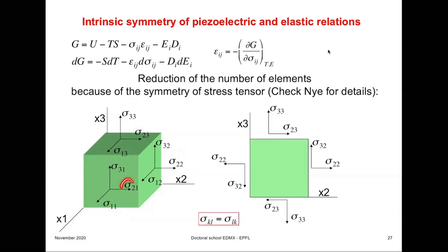And then we have shear components, where again the first index describes the direction in which the force is acting, and the second index describes the surface on which that force is acting. And the surface is defined by the axis which is normal to it.